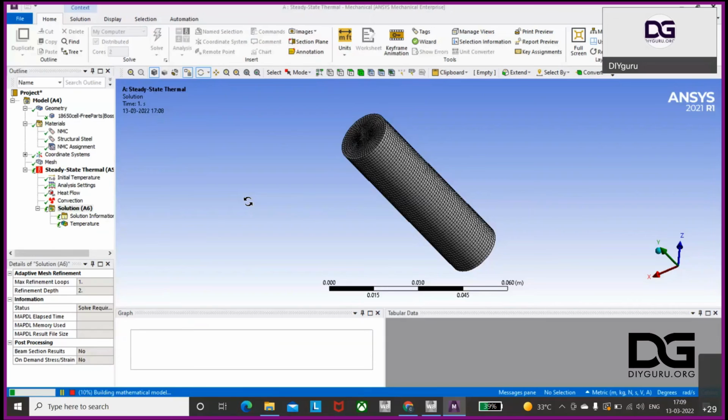It takes time with a finer mesh. There are two things, fine and coarse mesh. Fine mesh means that your element size is very reduced, and the element size and quality is very fine. Right now, this is at mid. And coarse mesh is like the one which I showed you with 5 mm, where you can see the lines are very broad. At coarse mesh, the computation time is very quick. Once you go with fine mesh, it increases computation time, because now the solver has to work on evaluating every node element, at what temperature, based on this.